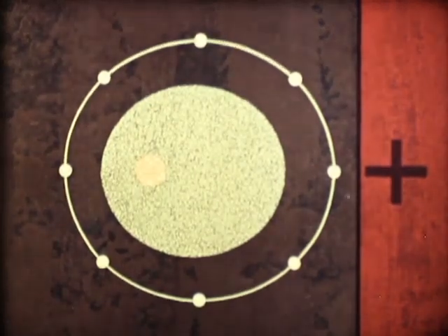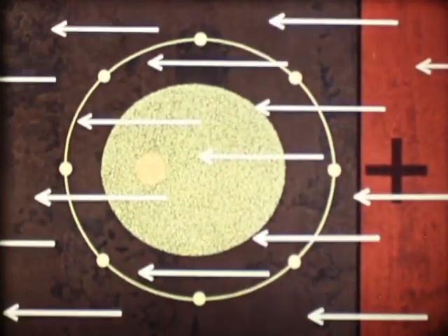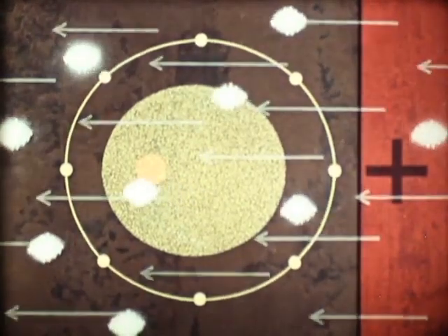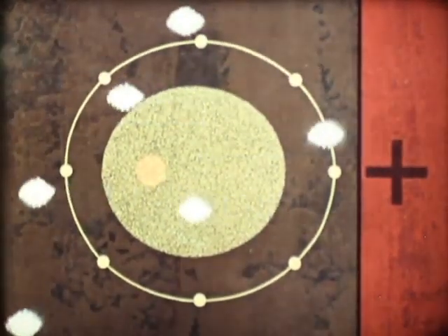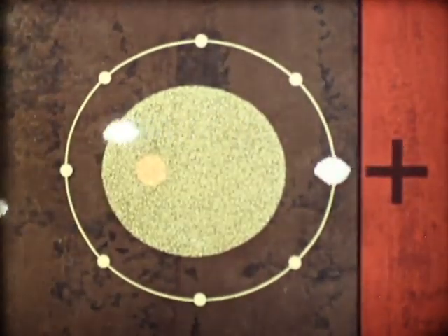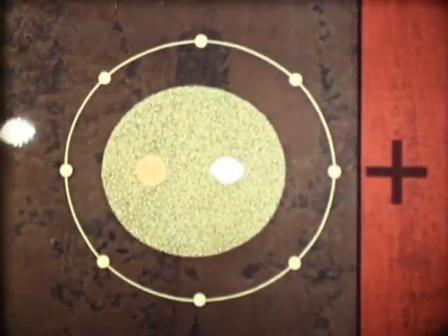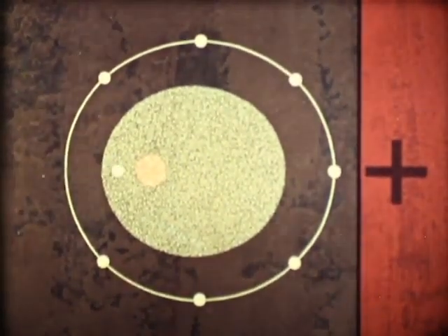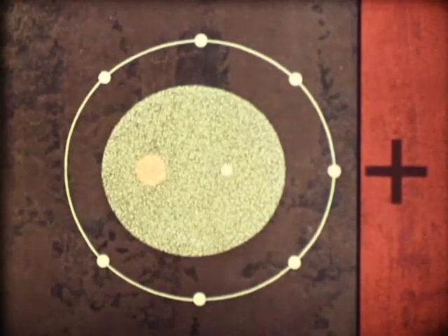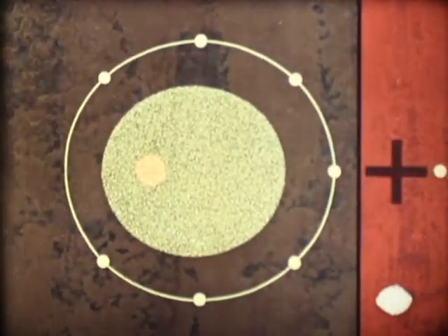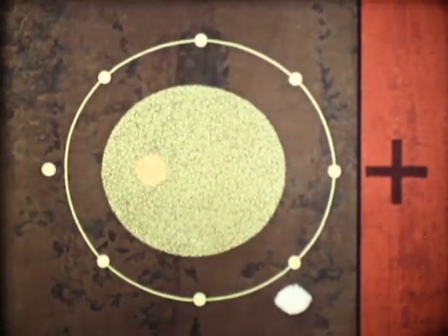However, the situation changes considerably when light shines upon the signal plate. Light can be considered as a flow of energy quantums or photons. They penetrate the tin oxide and are absorbed by the photoconductive layer, just like the photon you now see passing the nucleus. Its energy sets free an electron which now moves to the positive layer. The following photons produce a similar effect.